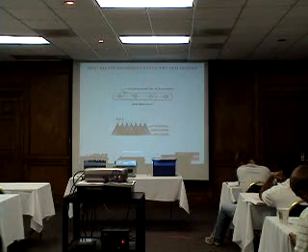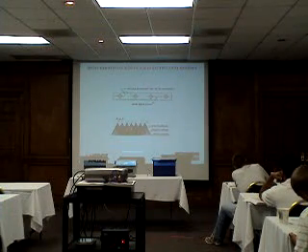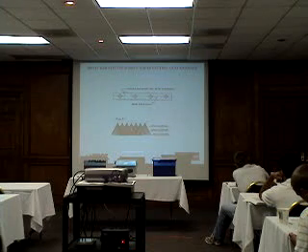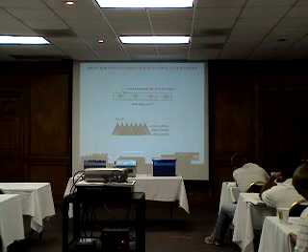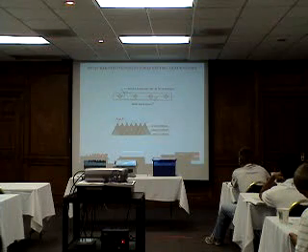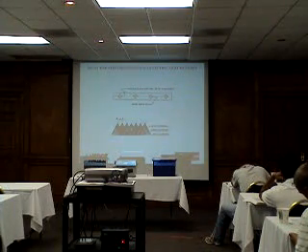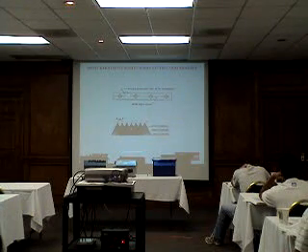As you see here, there's different coverages. You got your single, double, triple coverage. We do not specify any particular coverage. That's up to the contractor. The only thing we say is, Mr. Contractor, we want a good uniform coverage over the entire width of the area that we're going to pave.